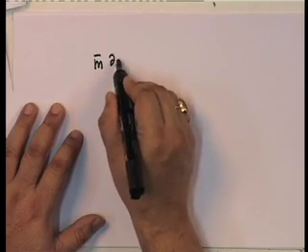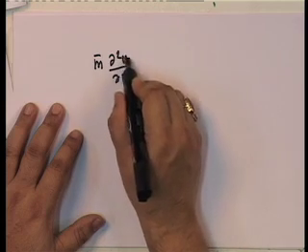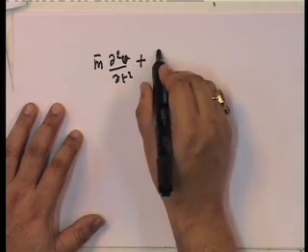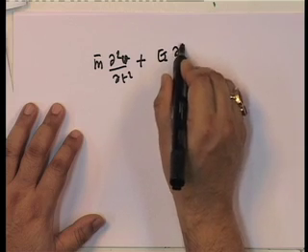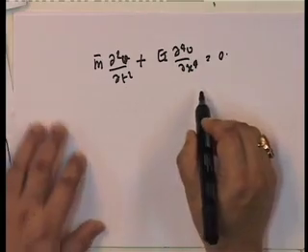Okay. Similarly, I will just write down the equation that I have. Let us look at the simple flexural vibration. Simple flexural vibration is what? It is given in this format. It is given as m del squared u by del t squared plus E I del fourth u by del x fourth is equal to 0.